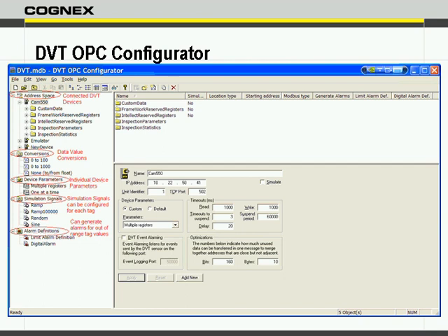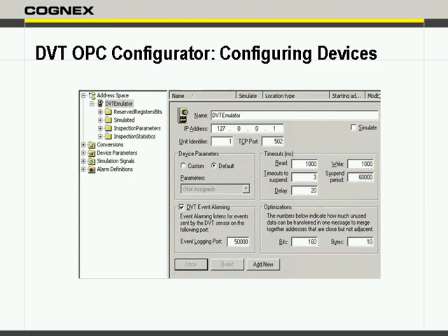It also controls how that data gets interpreted, for example, being able to swap words within your data value, and that will come in handy in some cases when we're communicating floating point values and even integer values. So any 32-bit value, you will have to do this, and we'll look at that later.